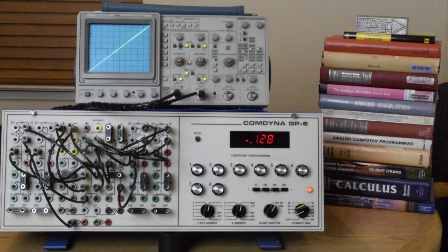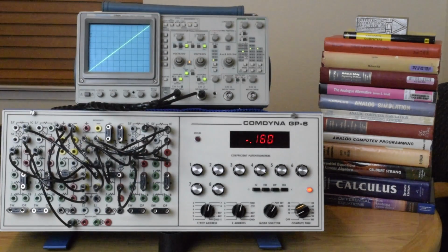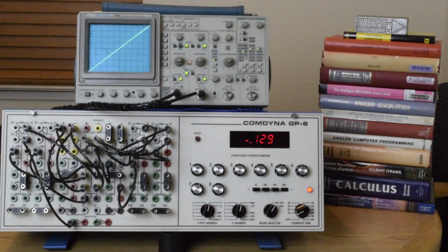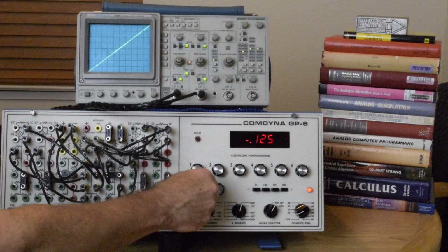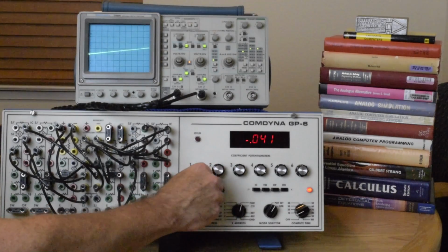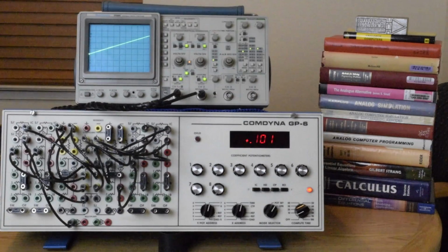But first of all, we'll talk about the simpler output, which is the voltmeter, I should say. It's not a multimeter. As you see, the voltage is varying on the voltmeter, and that's because I'm running in what's called repetitive operation mode. I do that because that gives us a quick update of the oscilloscope. Typically when you're analyzing a problem with the oscilloscope, you can get immediate results in the repetitive operation mode.